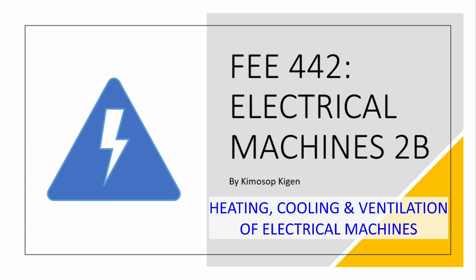while taking into consideration the heating losses. This is because in normal operation, an excessive rise of heat will lead to a deterioration of the insulation within the windings of the machine or within the components of the machine. In which case, if you have a total breakdown of the components of the machine, you will then end up with short circuits and your machine will stop operating as it should.